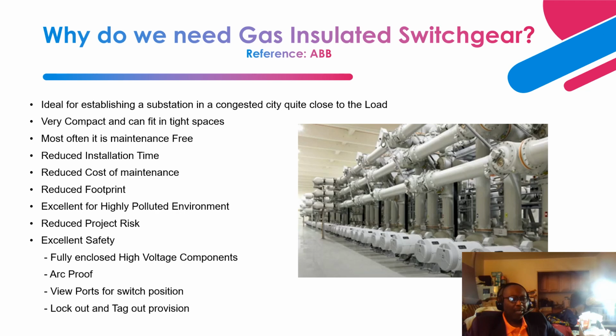Secondly, it is very compact, right? And as you know, for these congested, highly populated cities, space is a premium, right? You have tighter spaces, so it becomes applicable to think about implementing a gas insulated switchgear. Most often than not, the OEMs, the manufacturers of these gas insulated switchgear, will indicate that a GIS is maintenance free, but it's quite close.